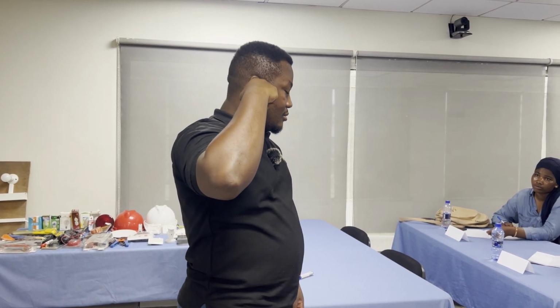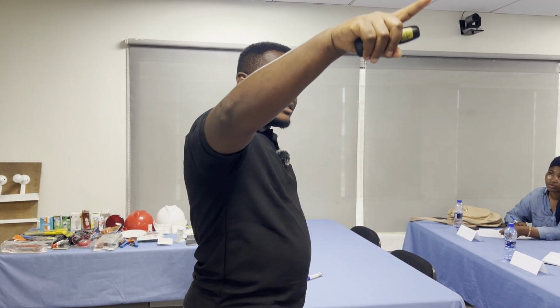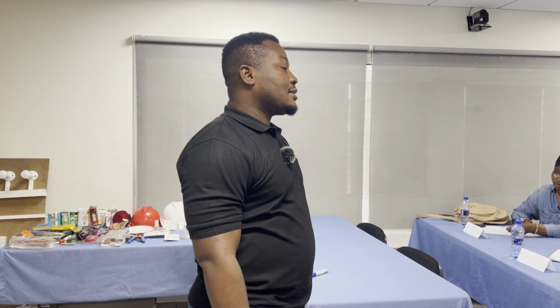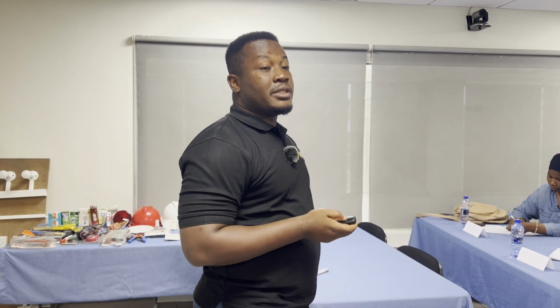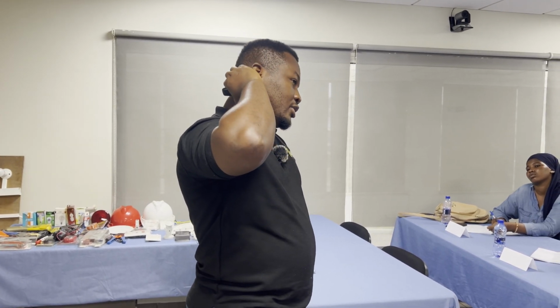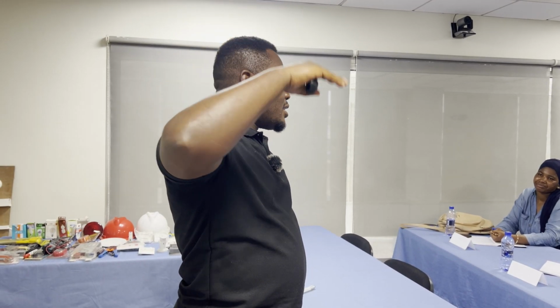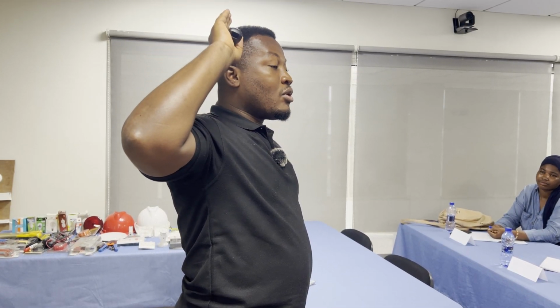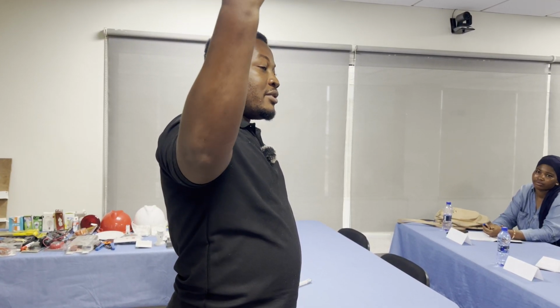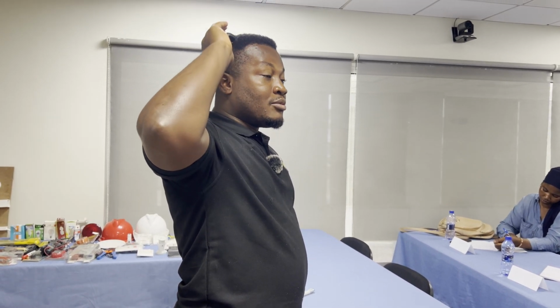For a ring circuit, it goes, and then there's a cable that's returned to the DB and comes to the same breaker. We use that for certain reasons. One of them is when you are constrained with spacing in your DB and you have a lot of sockets to do. For ring circuits, it's advisable to do from 6 sockets upward. For radial, up to 4 is fine. If you go 5, don't go more than 5. For ring, between 6 and 8.